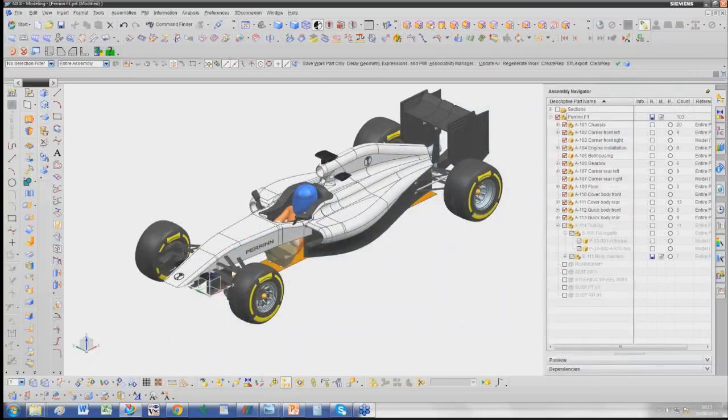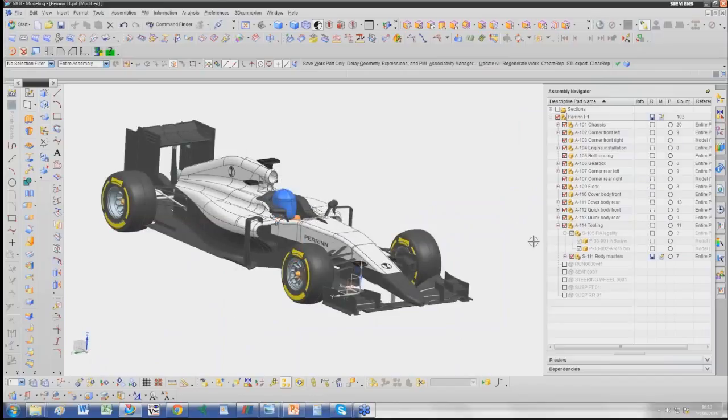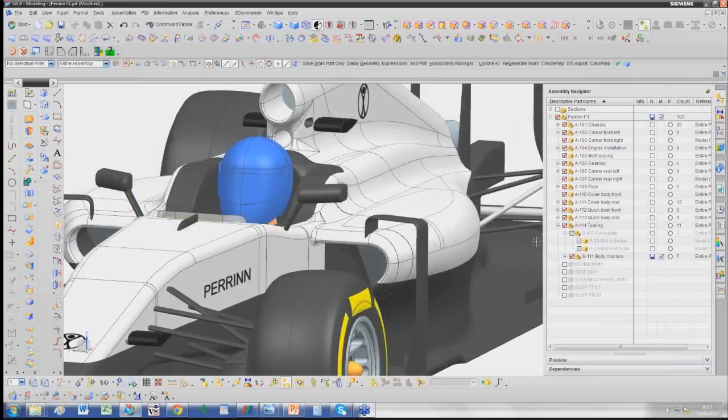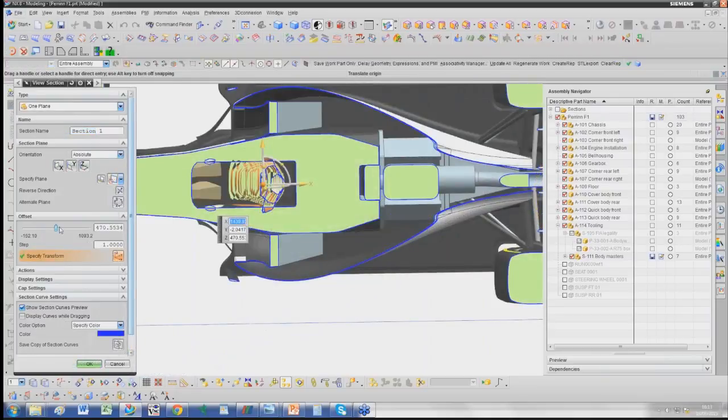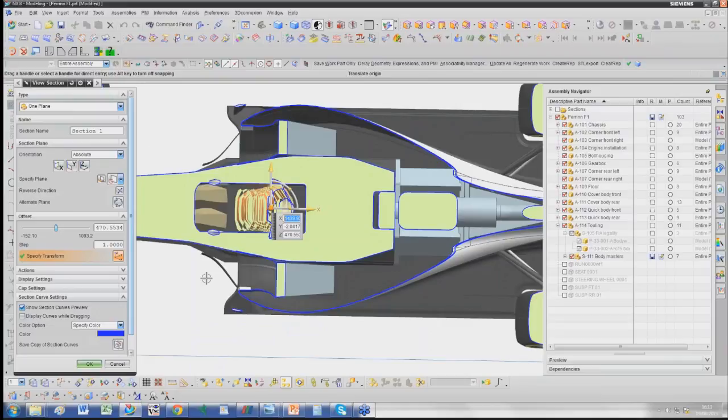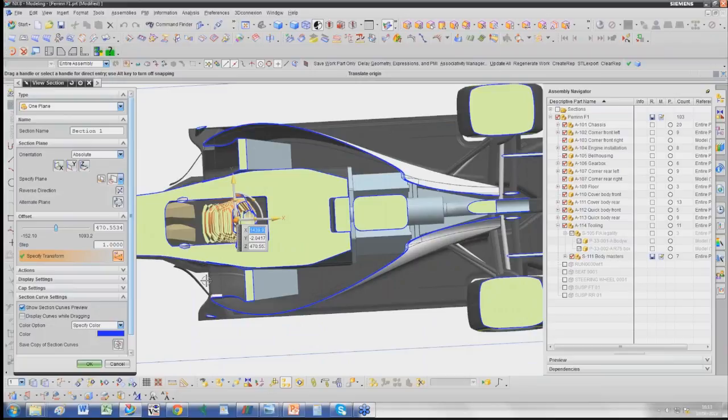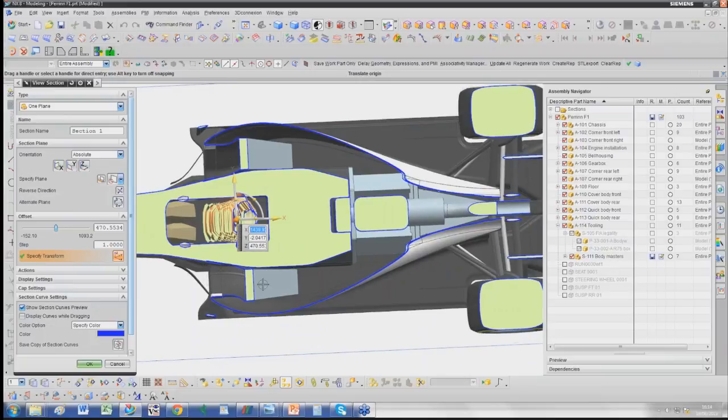The main model is having a radiator. So if I slice the car, you can see that, and that's very easy to do in CFD, and we will do it further on the SimScale platform because this makes the simulation much more realistic as well. But the flow will come in, go through the radiator, that will effectively simulate a pressure drop, so the air is going to be slowed down through the radiator, and then go into the engine bay. You see the engine here, and then come out there.